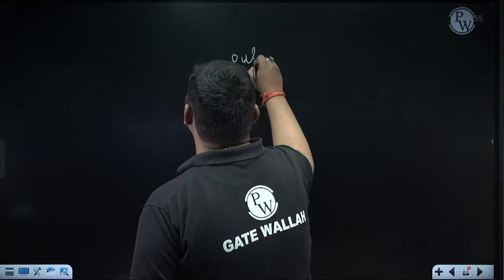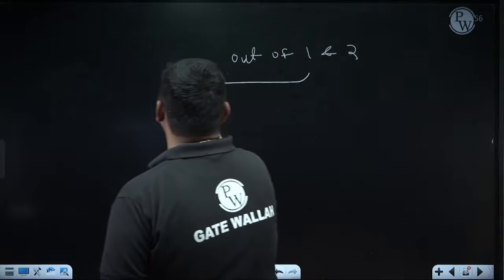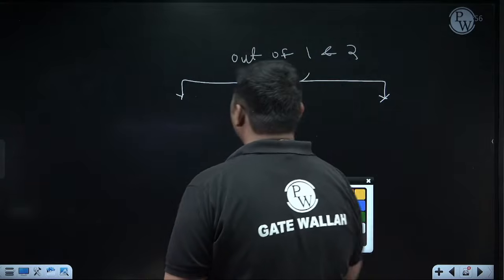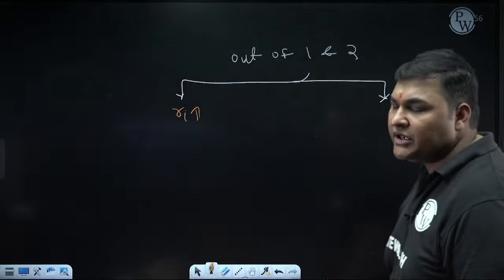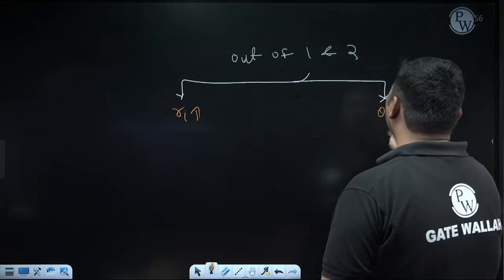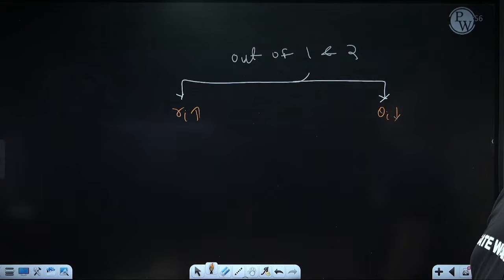Now we have to find out, of 1 and 2, which rivet is the overall critical or worst loaded rivet. So for that, for rivets 1 and 2, we'll calculate two things. First, Ri. Ri is the radial distance of the center of that rivet from the centroid. We will see for which rivet Ri is more. Second, theta. Theta is the vector angle between primary shear and secondary shear, and we'll see for which rivet the vector angle is lesser.